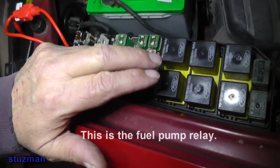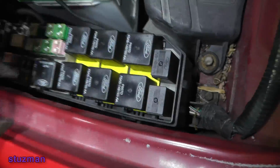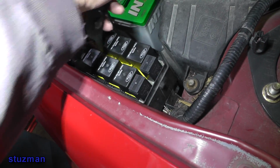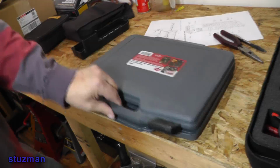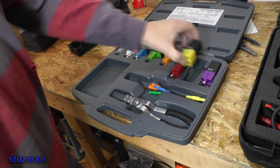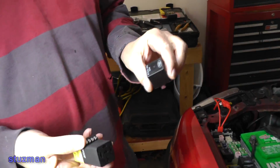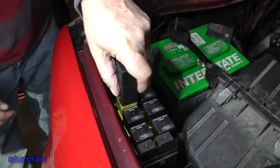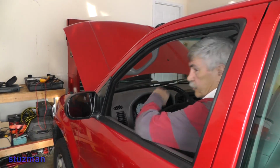Next thing we want to do is check the relay contact and see what kind of condition that is. To get access to the pins, of course, we need to pull out the relay. Now, since the relay is pushed all the way down, we're going to use an adapter so we can bring the relay up. So, with the relay and the relay adapter, let's put them in, and we're done there. All right, let's crank up the engine.